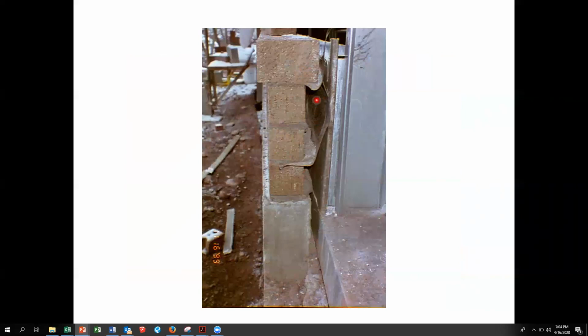There's the flashing. Remember the flashing that we saw originally? The brick was not up. So the flashing comes down and it goes into the mud joint. It really should come all the way out to the face of the brick. We'll show you that next semester. The fact that there's a little lip, see that little lip of the concrete wall? That's where they got their concrete wall out of line and out of tolerance. This wall right here should be flush with this wall. Okay, now there's a little bump out there, so that might be the reason. I can't remember, it's been so long.